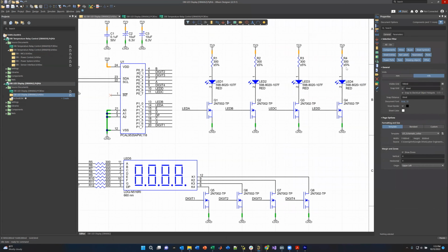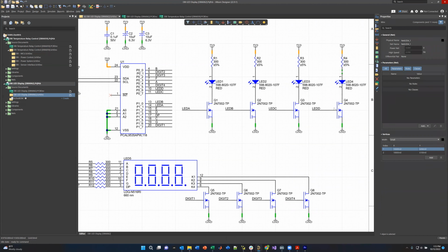So you just do a little mathematics using Ohm's law and nodal voltage analysis, because the node voltage here is going to be the forward voltage drop when this transistor is turned on. When the transistor is turned off, there's no current flowing, so it doesn't matter. So when the transistor's on, this terminal's at ground, which means this node's at roughly 2 volts, and then I can compute what resistor I need here.